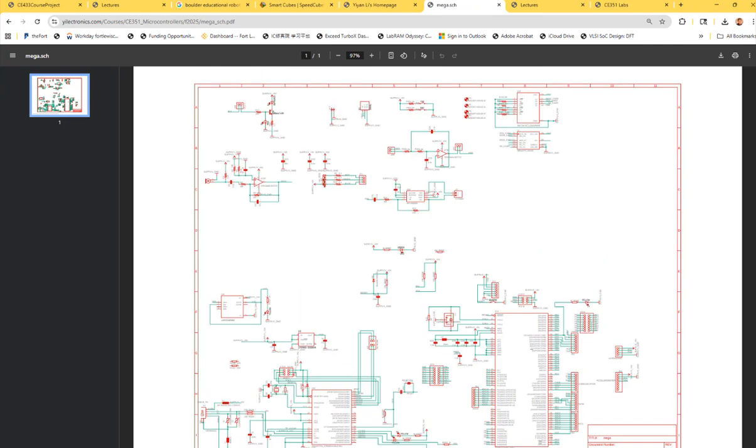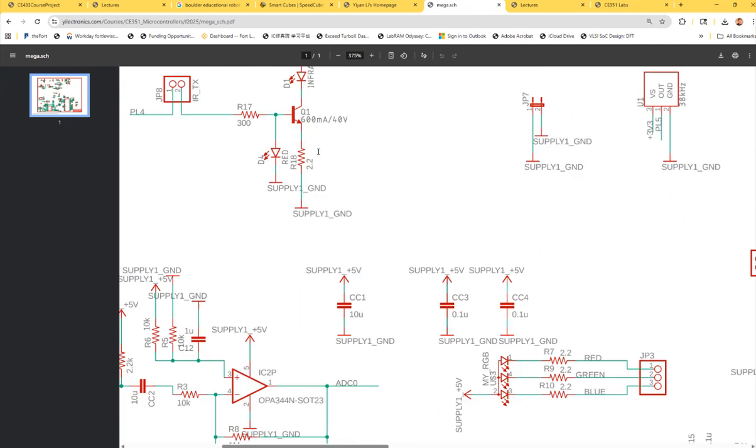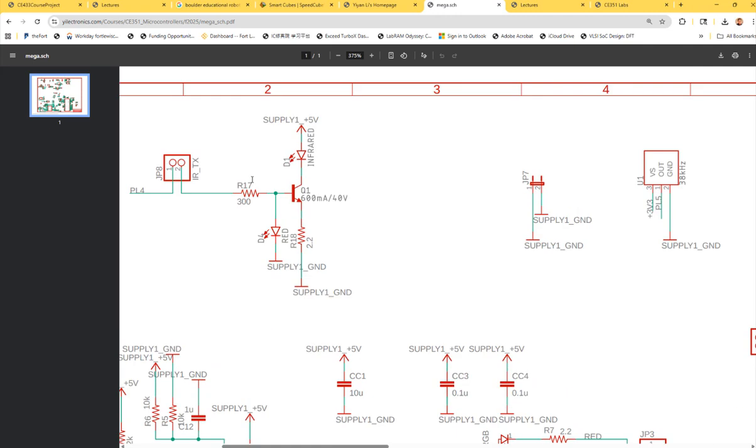Because 45 is delivered to here, that's 45, but your probe here is not working. What's happening? Some of the soldering in the middle is not happening, or the traces or something got damaged. If this one works, you can probe this point and the other points, and see if everything works.